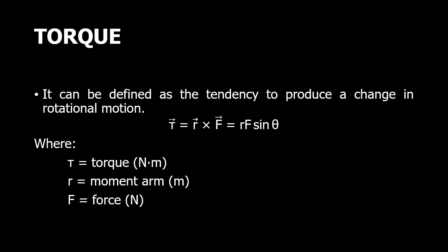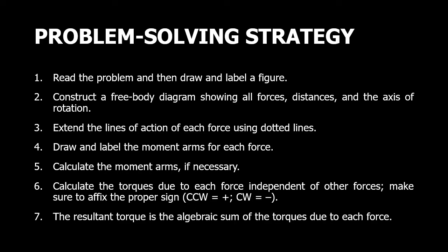The formula in order to solve for the torque is equal to R multiplied by F, or R multiplied by F multiplied by sine theta, where T is torque, which has a unit of Newton meter, R for the moment arm, which has a unit of meter, force is represented by capital F, which has a unit of N.